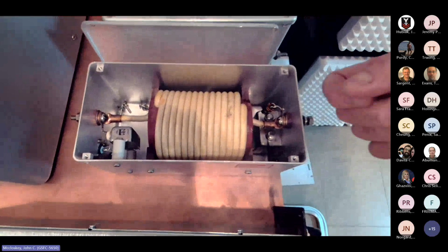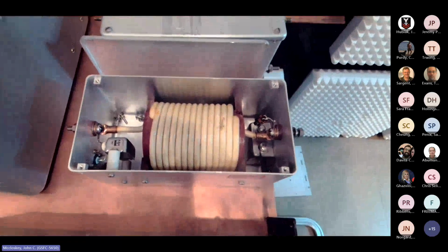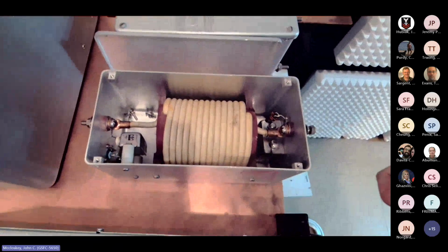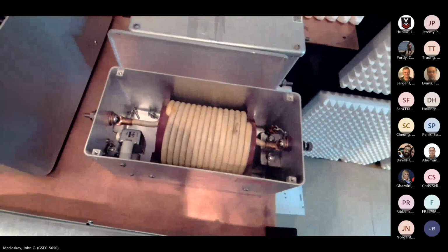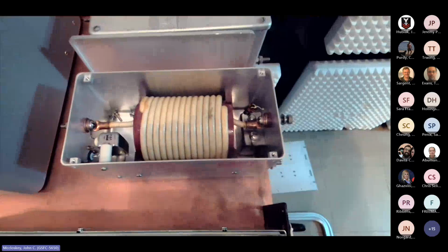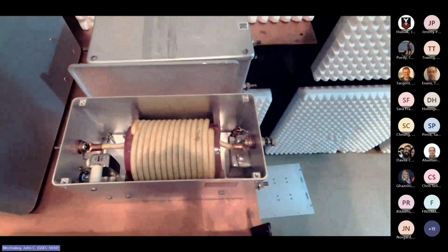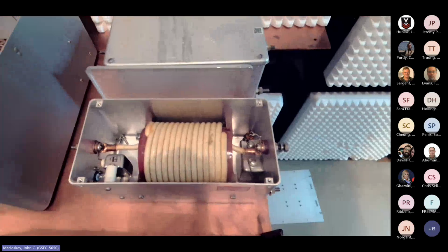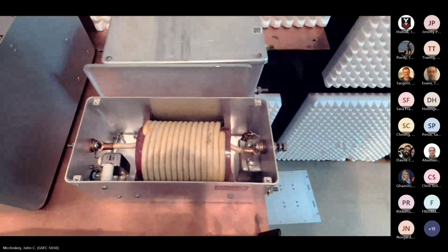Okay, so just 5 microhenries is a lot of inductance. Parasitic inductance tends to be on the order of tens of nanohenries, maybe a couple hundred nanohenries if you're talking about a long run of wire. Just for comparison, as I mentioned, 1 microhenry per meter is what you get running a wire 5 centimeters above a ground plane.